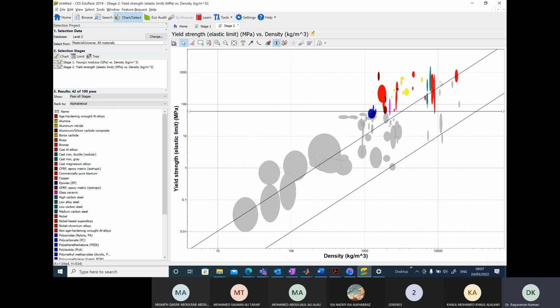We also have other alloys, maybe tungsten alloy. This is silver, obviously we do not want to use. There should be also titanium alloys if you go for high strength materials. Not sure where it is here. So we have the titanium alloy. We can clearly see the yield strength is around 1 gigapascal in this particular case. Okay.